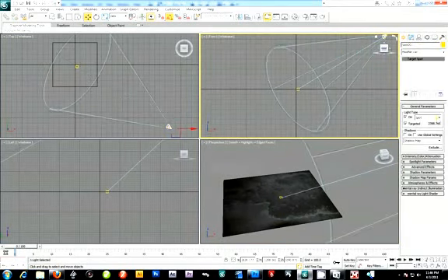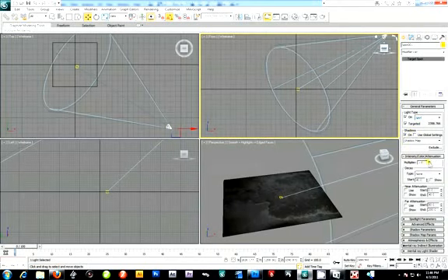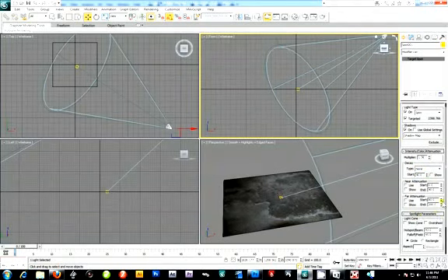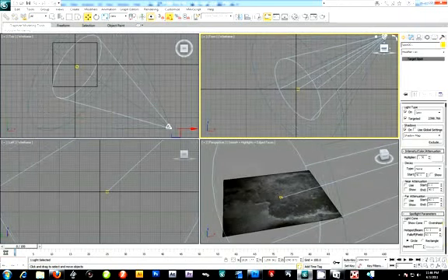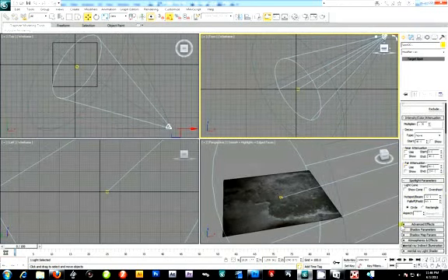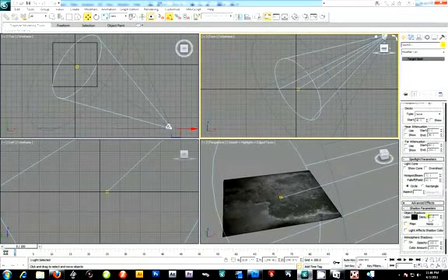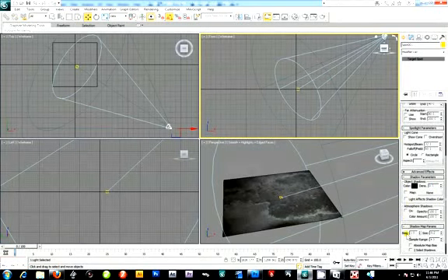Alright, so I'm going to turn on my shadows, intensity and color. I can probably crank that up just a bit. And I'm going to keep it at none for now, and then make sure my spotlight parameters, the hotspot and falloffs are spread out a bit. And then of course on my shadow parameters, I want maybe a 0.7. And then let's see, shadow map parameters, bias 0.1.